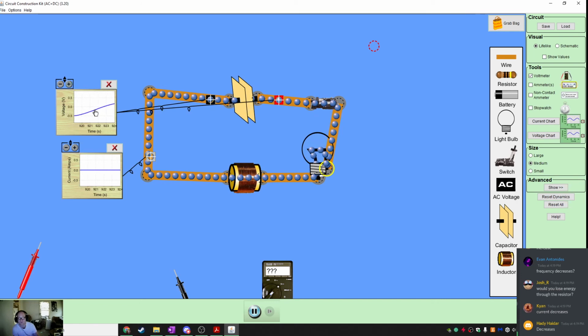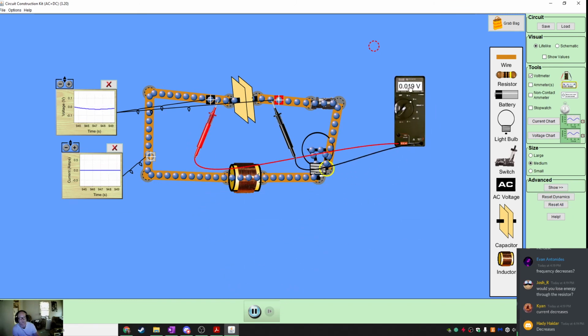So can you see that the voltage is slowly trickling out of the system effectively? Here, now it's at 0.25. On the other side now we're at negative 0.1, a little over 0.1. I'm zooming in here, but the current is basically going away. And you can see on the circuit, there's basically nothing left in there, right? And whereas we started with 9 volts of energy, now we're down to a very small amount. So small that the simulation isn't even drawing the charges on here anymore. But the peak voltage is getting smaller and smaller and smaller.